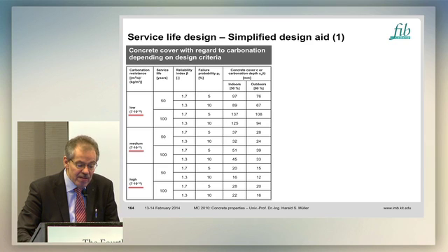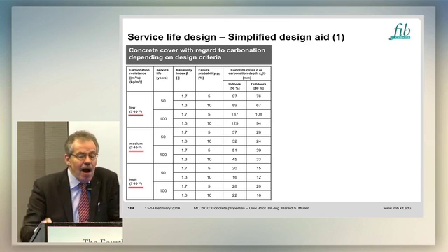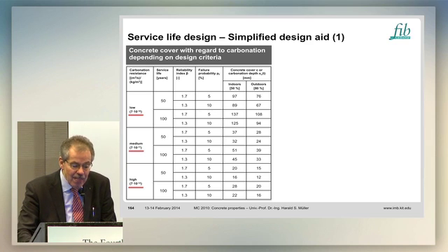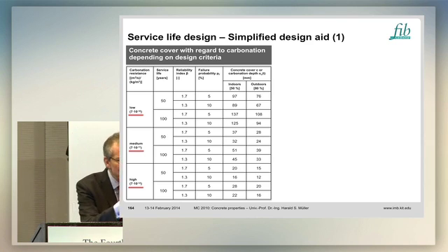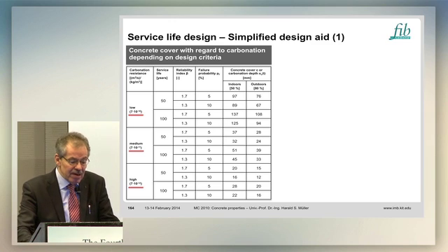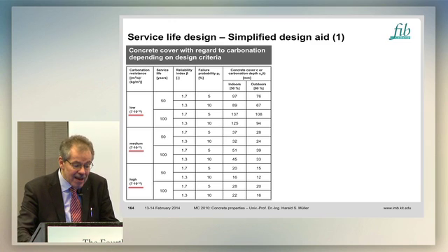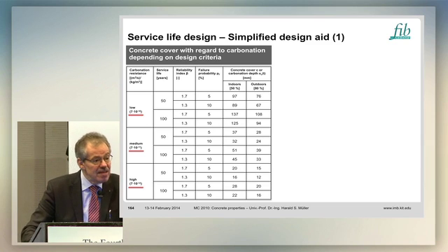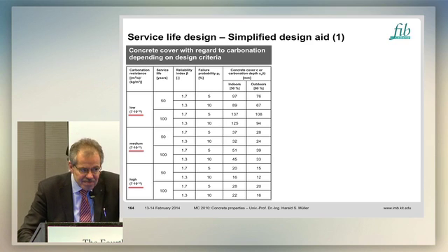And I also vary here the reliability index, how much damage you are willing to accept. And then you can calculate the concrete cover meeting these boundary conditions. See, this is completely different from what we had before. And now you can say, okay, but where can I take this carbonation resistance from? The answer is very easy: you should take an easy measurement in a laboratory. It costs not more than testing a cube.